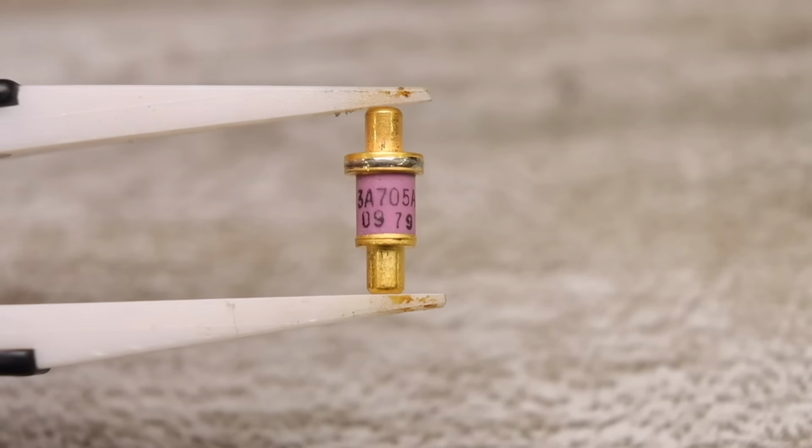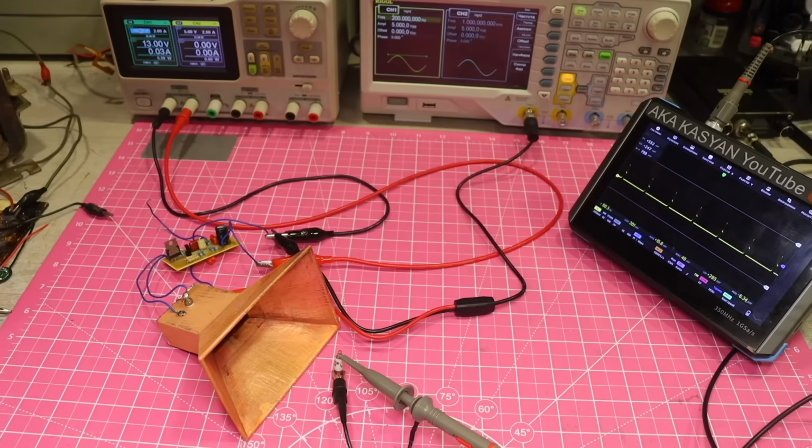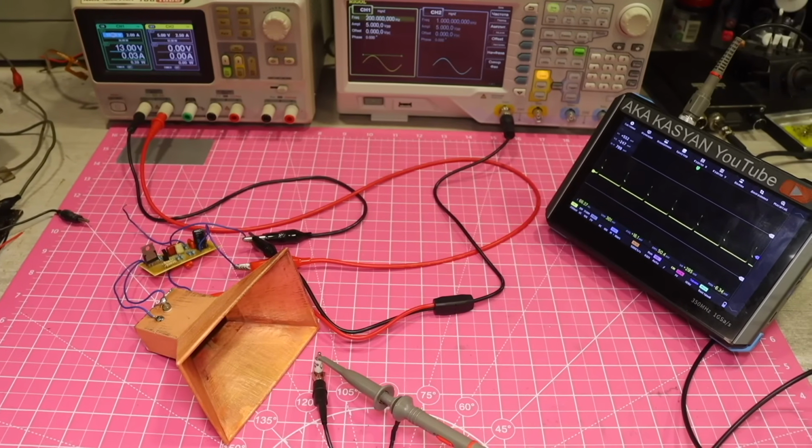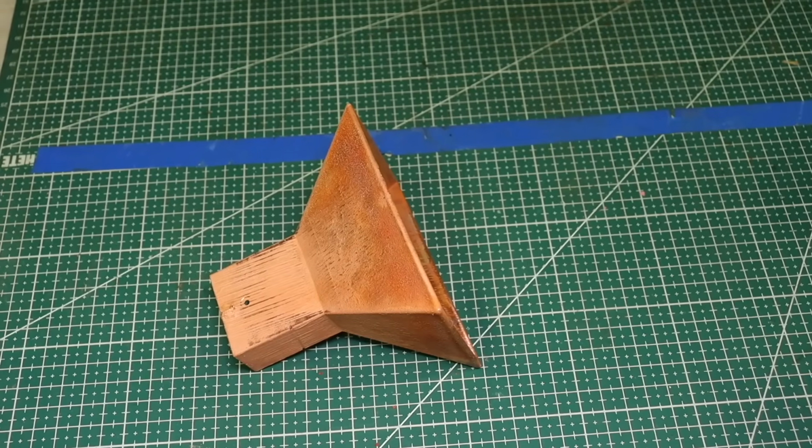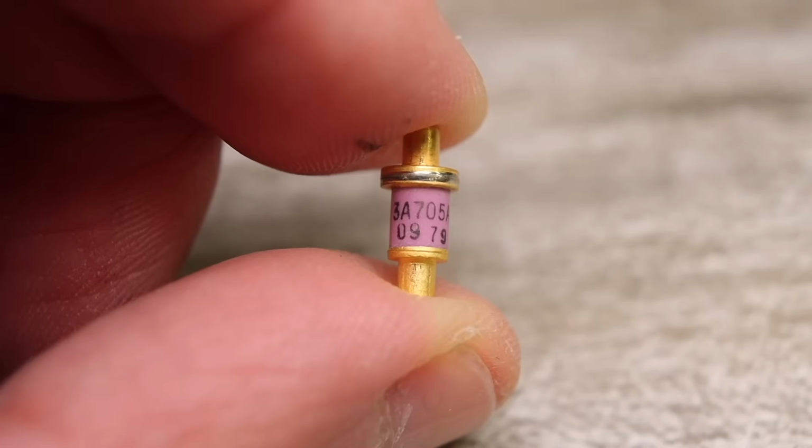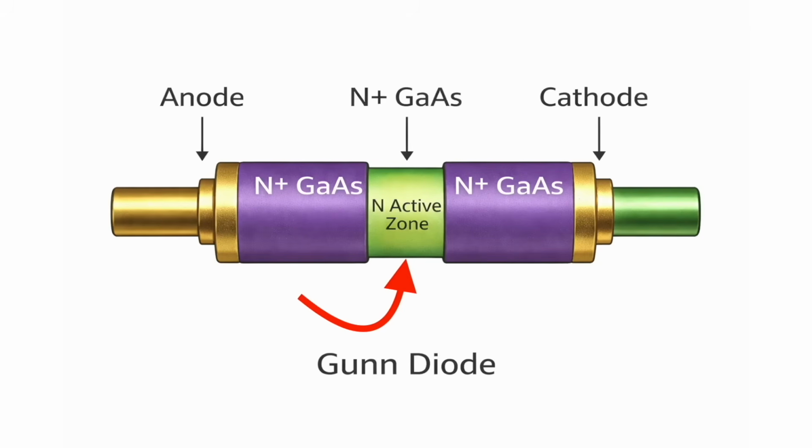From this, we can conclude that the Gunn diode itself does not set a strictly defined generation frequency. The frequency is determined by the external resonator. However, the maximum possible frequency is limited by the length of the active region of the diode's crystal itself. The shorter it is, the faster the domain reaches the anode and the higher the maximum generation frequency.